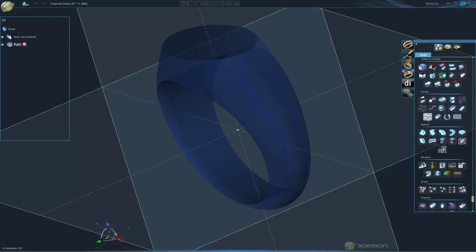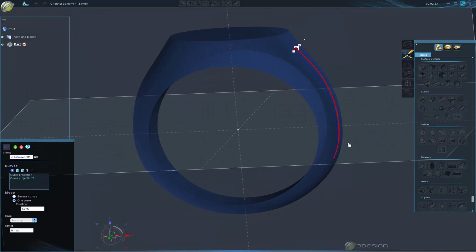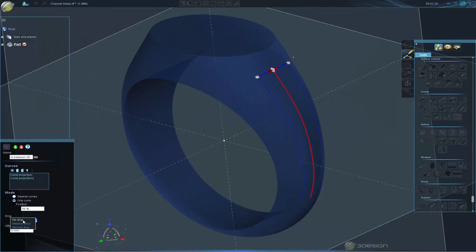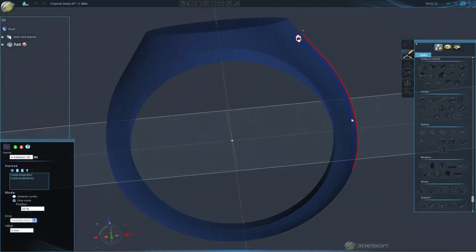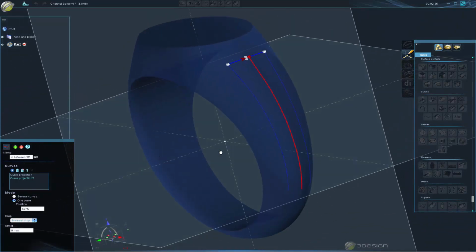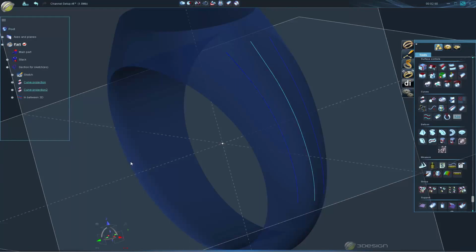In the old version, when you did an in-between, it placed your in-between directly between the curves. So it's not matching my surface. The new version, we have a drop option, so we can drop it to the nearest surface and actually get my in-between on top of the surface. So that's going to make setting channels and running text or whatever you're going to use this for easier. And then there's an offset built in, so you can offset that as well if you want to manually change the height of your curve. Okay. So again, little changes, but things are going to be much easier with that tool.